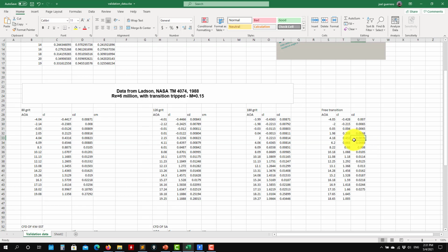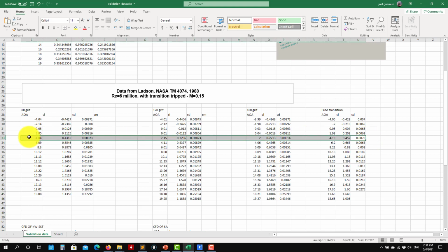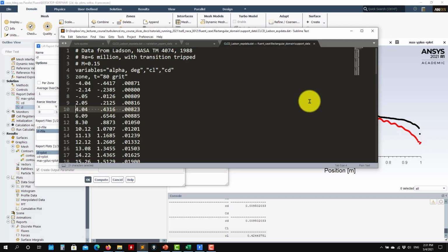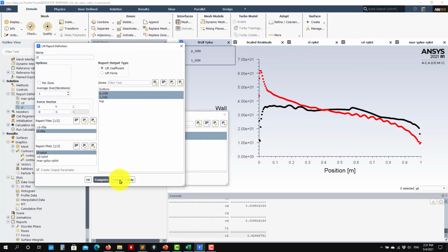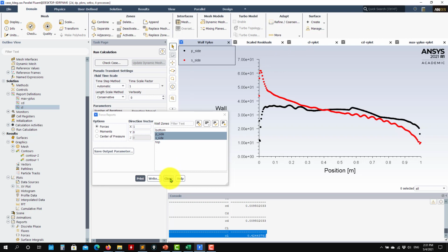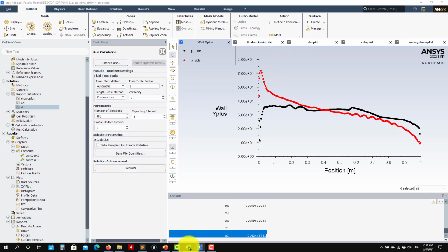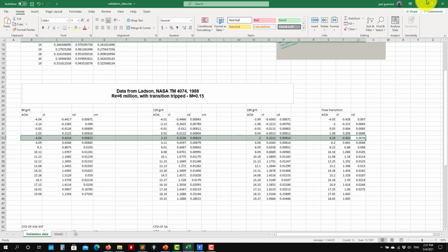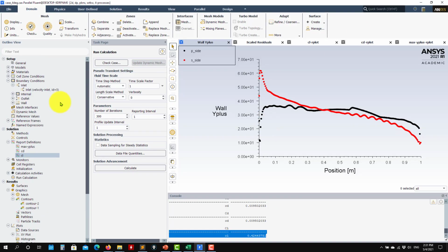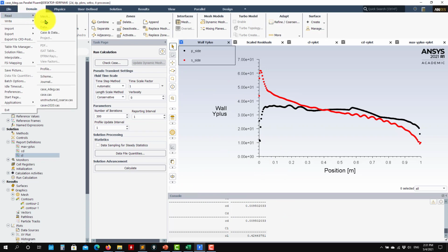The largest difference here will be for the drag coefficient. If you use this data, you will have problems validating, because you need more accurate meshes and solvers. Usually for natural transition, if you are interested in this one, it's better to use a transition solver. Here we're using the traditional turbulence models. So this is the first mesh, 4 degrees, and now let's open the other mesh.